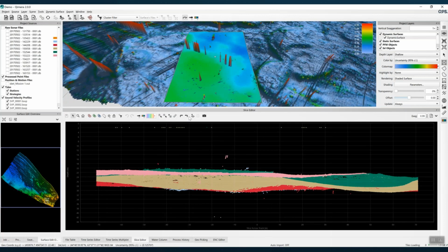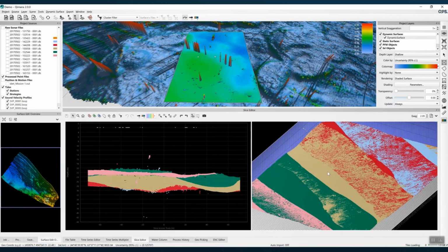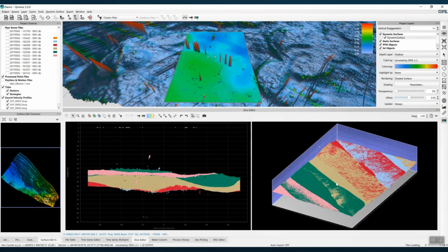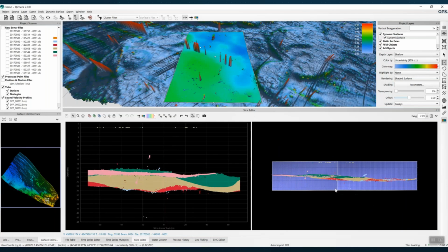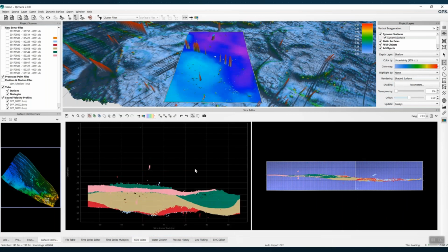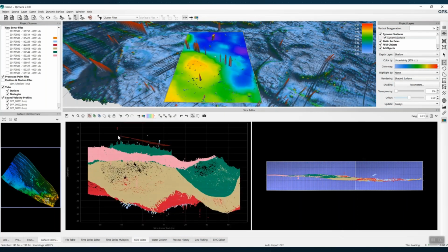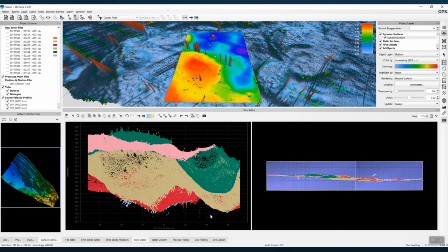And what I'll do is point out the new button on the console for where the 3D editor is launched from. So we're calling this the 3D slice. So to keep it separate from the 3D editor, you click on that button, and it pops up alongside by default. And this has the same mouse behavior as it is in the scene. So you can edit using the left mouse button, and you can pan and tilt using the shift key to modify your mouse actions. And you can edit in both editors. They both update, and so do the points in the scene.